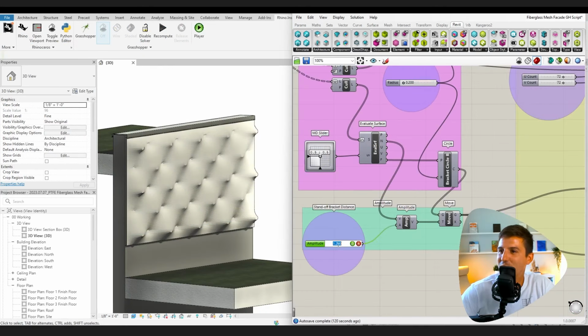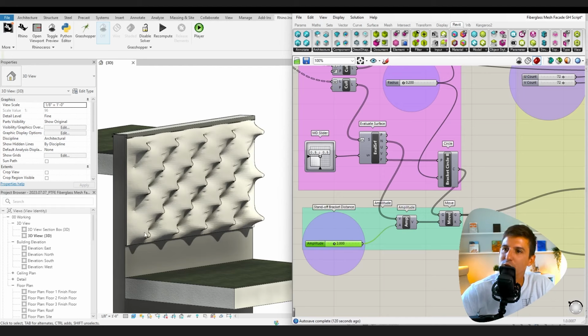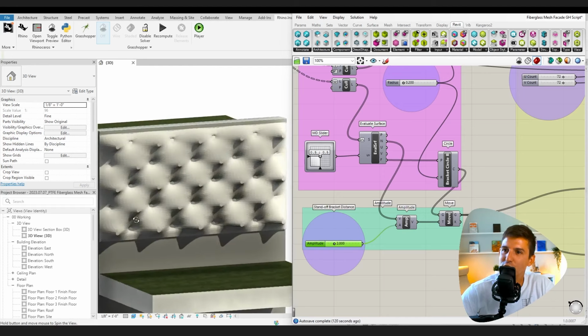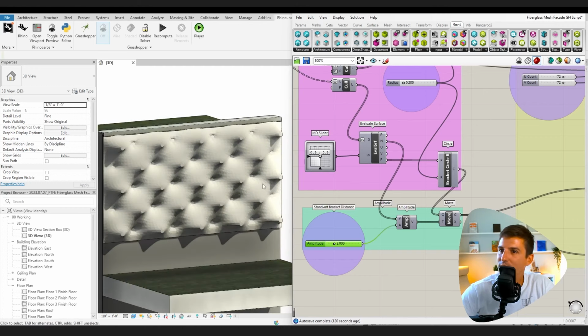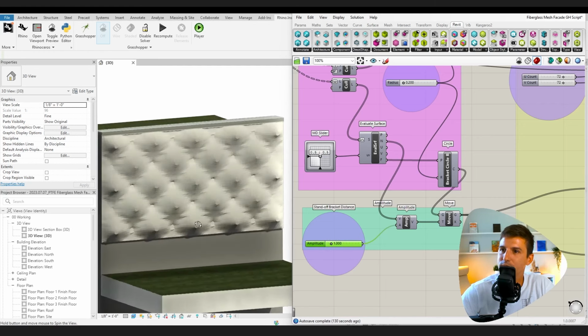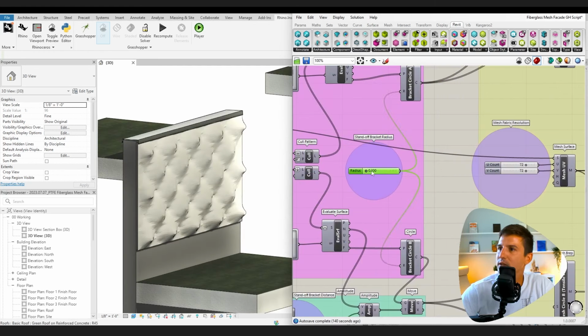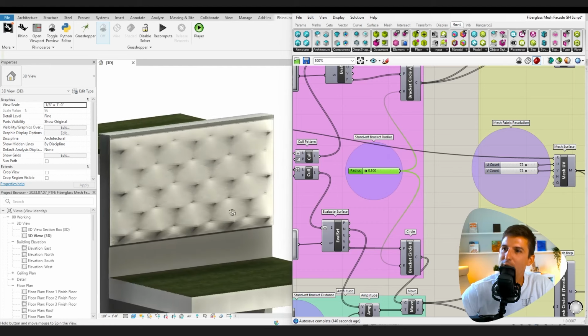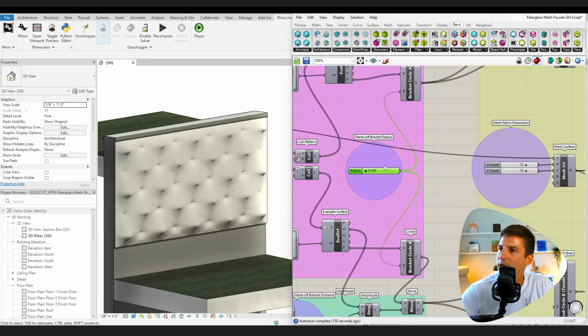Bracket distance. So here I can go and change that, let's say to 2, and check that off. Now that's more about 2 feet out. So it's going to become much more drastic. And if I wanted to change that back down, I can just say 1. It'll be more subtle. Change the radius here to, let's say, 0.1, then the diameters on those brackets pushing and stretching out the fabric will become smaller. And if we change that to 0.3, they'll become more pronounced.